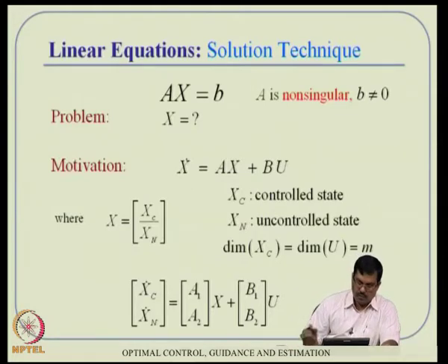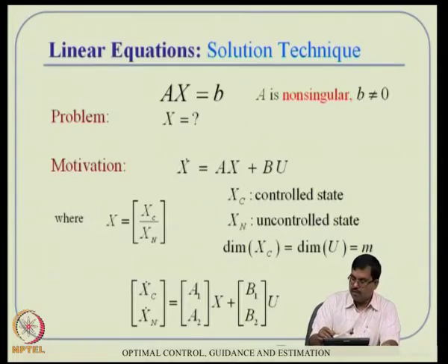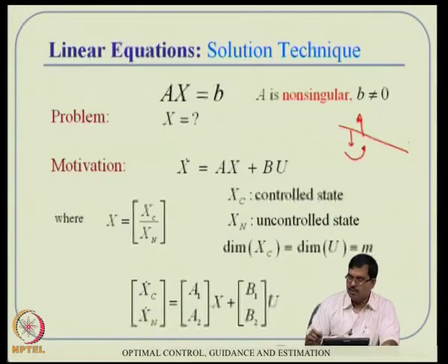In a small diagram, your CG will be somewhere here and CP somewhere there. So, that will give us some sort of a turning moment, and you want to cancel that by using an equivalent moment. That means you really require some small elevator deflection.